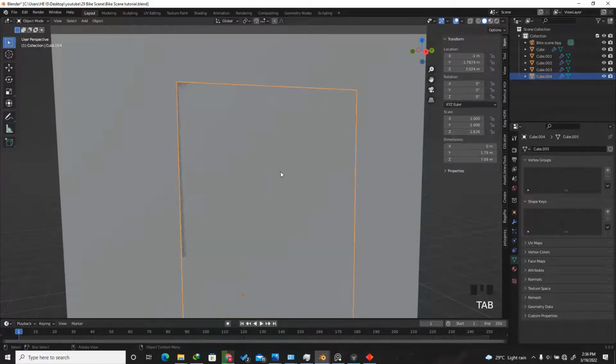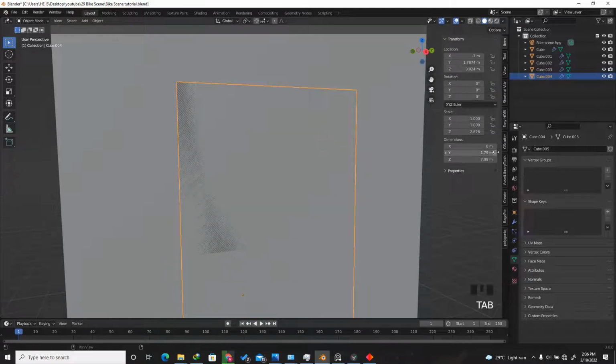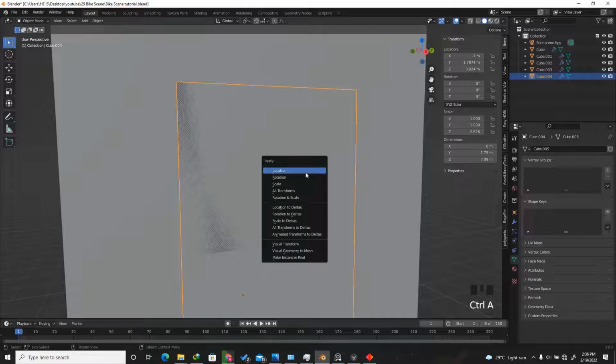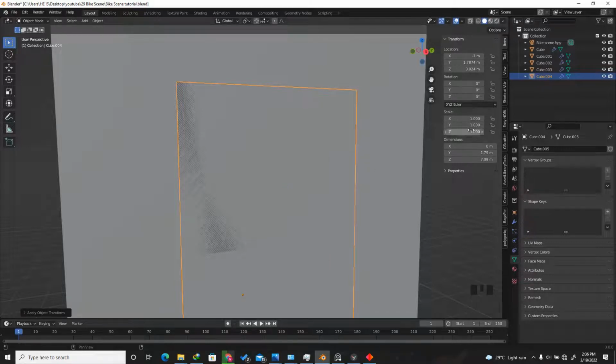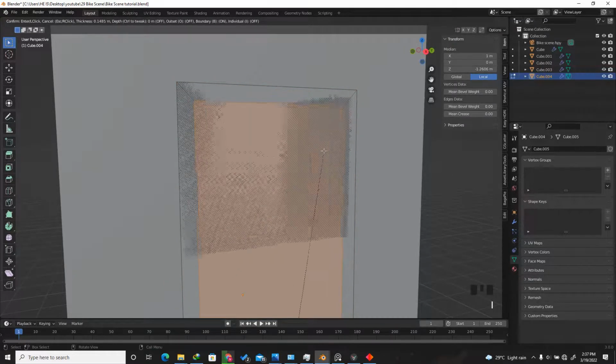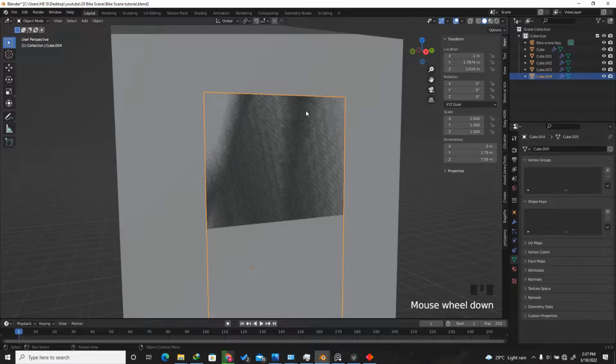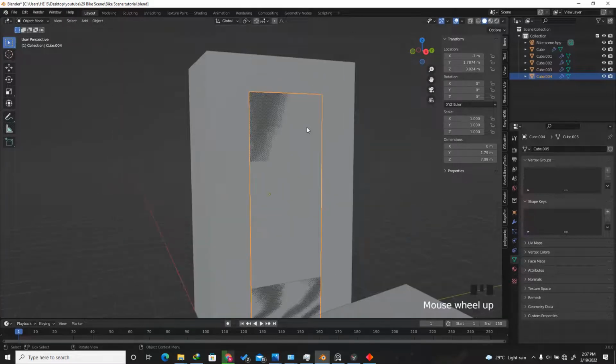The reason for that is if I get outside of the edit mode, as you can see, the scale of the Z axis is not 1 as the X and the Y axis. So this needs to be 1 for the manipulation or for the modifiers to work properly. So for example, if I get inside of the edit mode again, let me press Ctrl Z, and as you can see, the scale is not applied. So press Ctrl A, and if I select the scale, as you can see now, the scale is applied. So if I get inside of the edit mode again, if I press I, now as you can see, the inset is being applied correctly in the vertical and the horizontal part. So make sure that the scale is applied whenever you are doing anything after you have scaled any of the objects. So I'm going to hit Ctrl Z to get to my previous position.